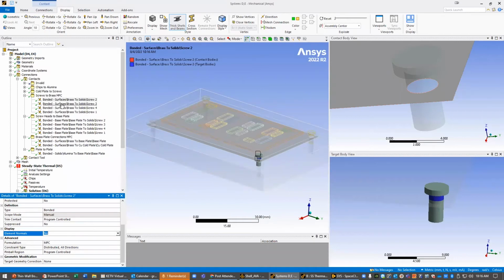And so for each of these, anything that is in contact with your two-dimensional shell object now needs to have MPC contacts and has to use this constraint. You have a restricted number of restraint types, which I'll get to in a minute.